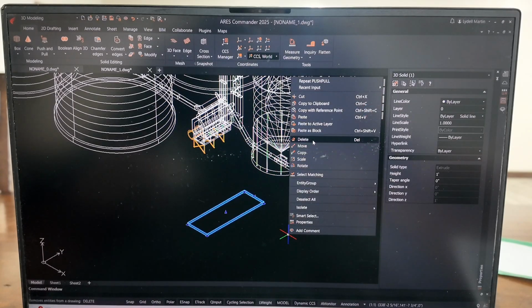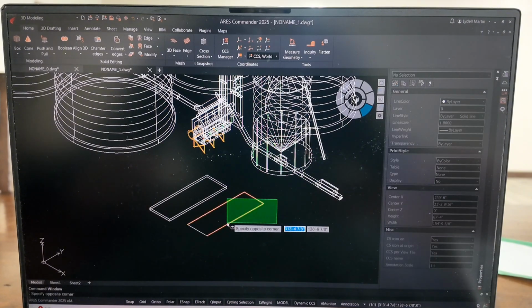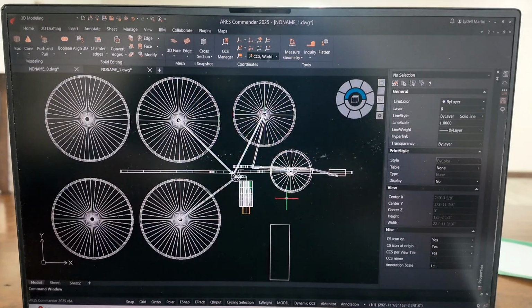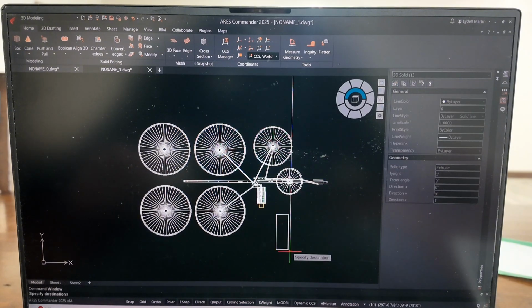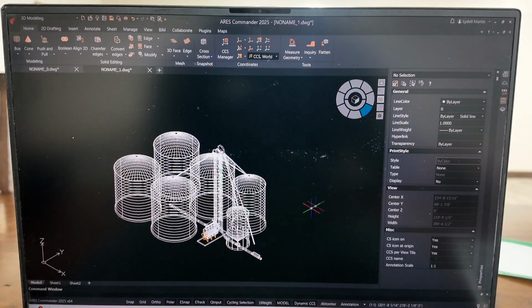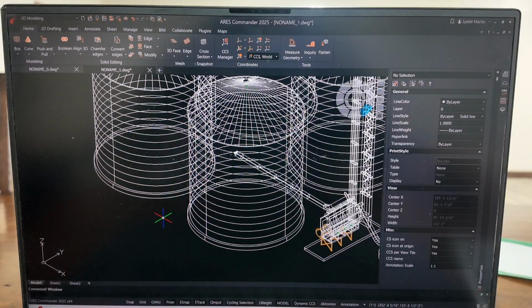This is not concrete, this is layout. So just because I have a measurement for concrete on a drawing like this does not mean that's what I recommend. This is for layout. So our dryer and elevators will set on that pad. So this is what dimensions I would use for concrete, but not how deep. Depth is not accurate, but the area is accurate.